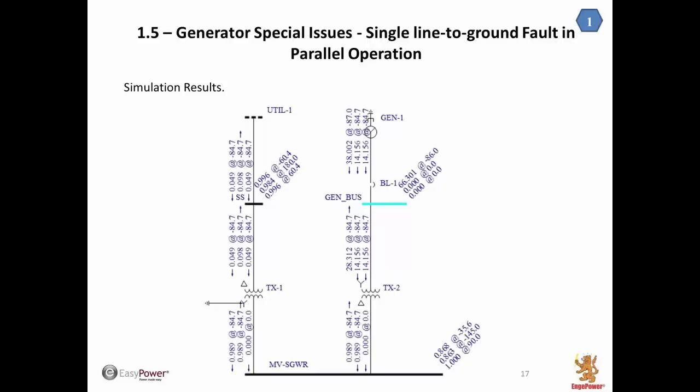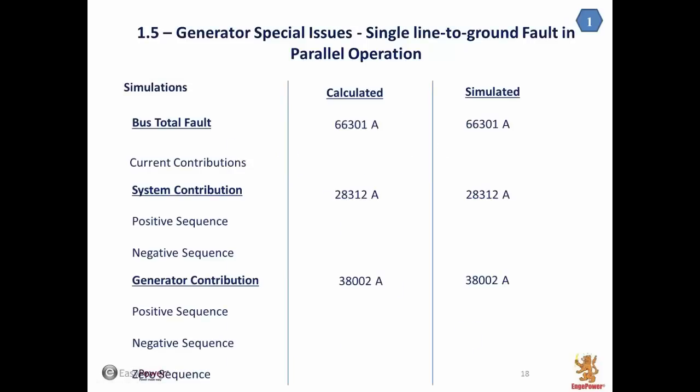This value we calculate here is higher than the simple calculation using the generator impedance. So it's very important to perform the simulation and sum the currents of the three phases. If we sum this, the angle is practically the same, and you see that the value will be very, very high. So the total bus, the calculated and simulated are the same. This is very important.